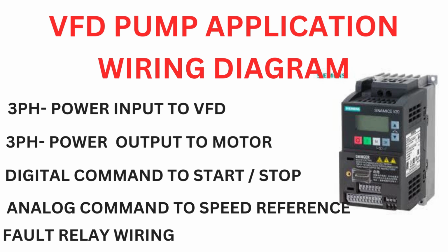Generally, based on the application, wiring can differ for the power circuit and the control circuit also. So you need to focus on which application, and what kind of wiring we are going to do. We need to confirm that while selecting the application and while selecting the VFD.